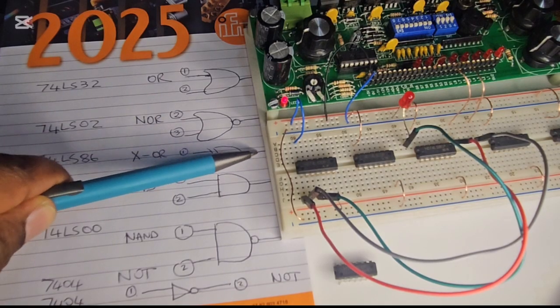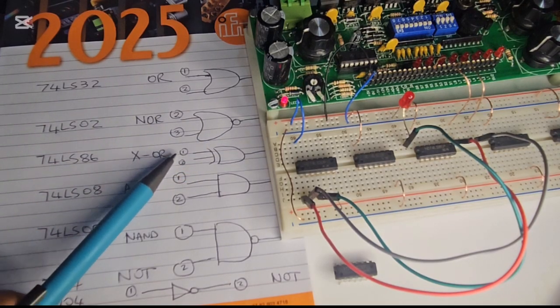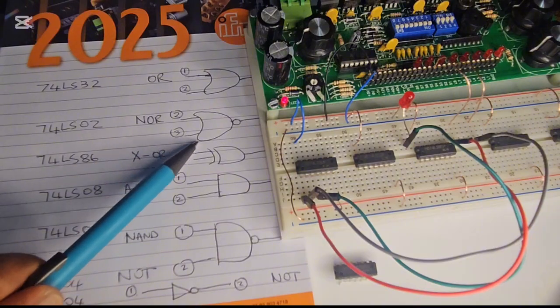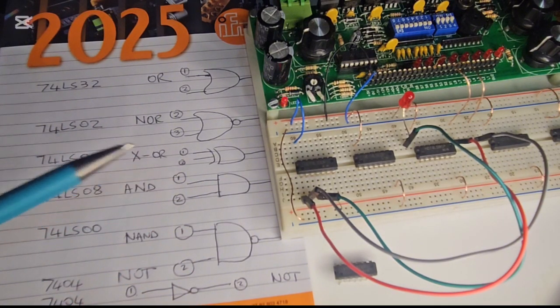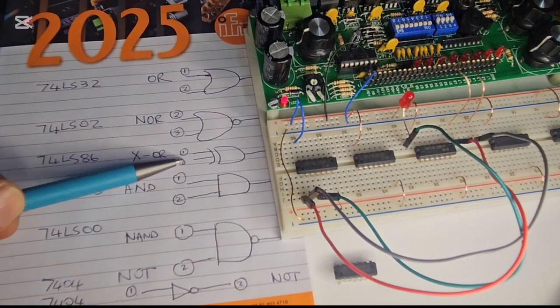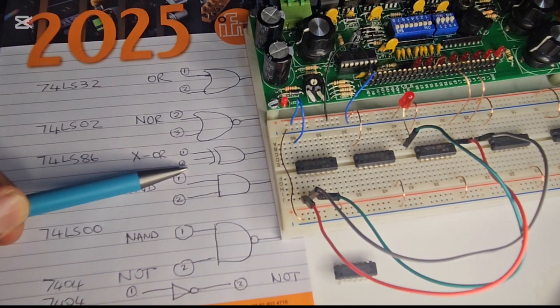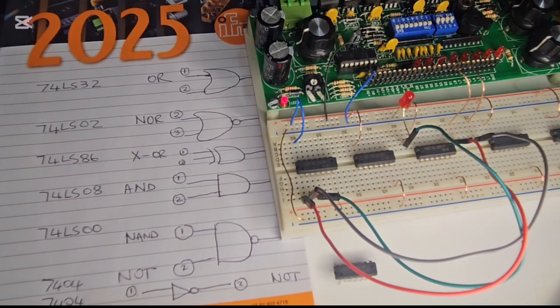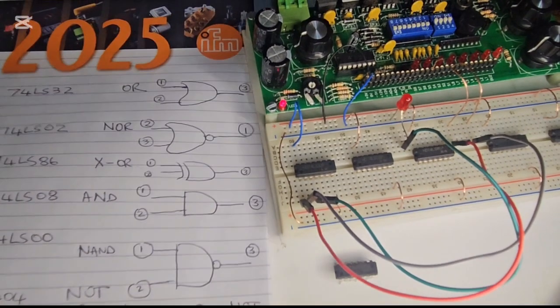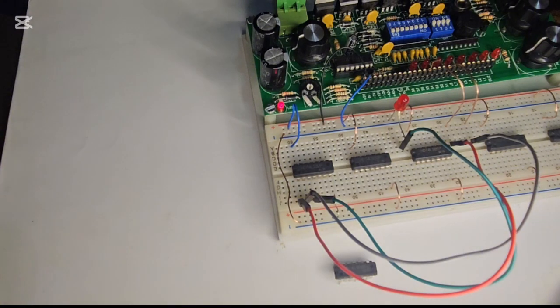Off gives me an off. But if this input comes on, it gives me a 1. If both are true, it still gives me a 0. So the exclusive OR wants my inputs to be different. In a sense, if both of them are true, it will give me a false. But if one of them is on, it gives me, let me just bring in the truth table so that this one can be clear.